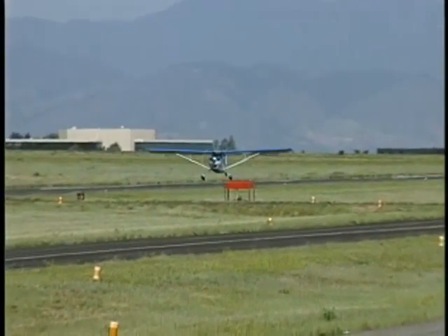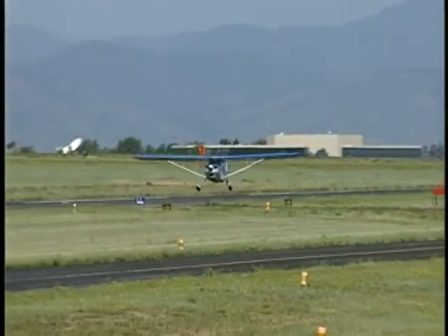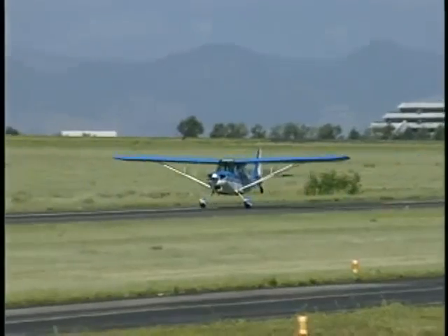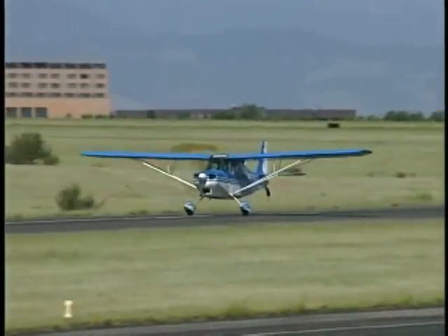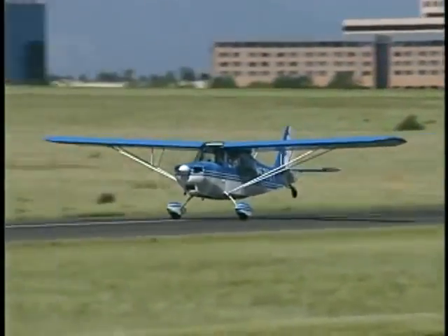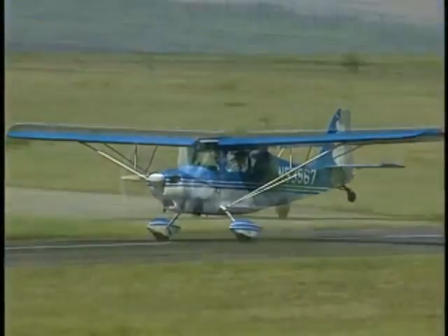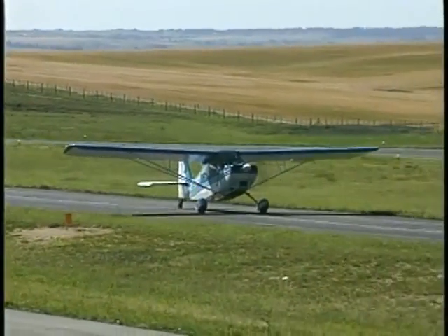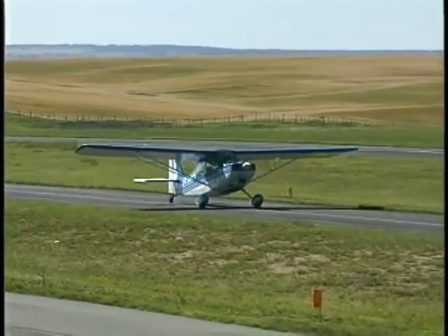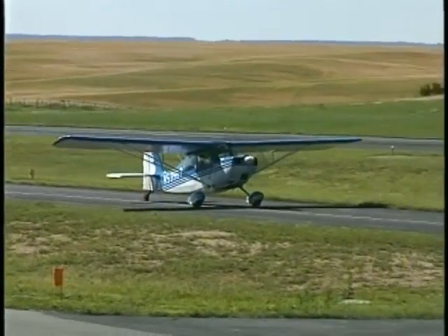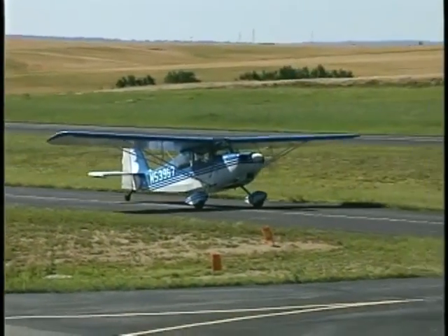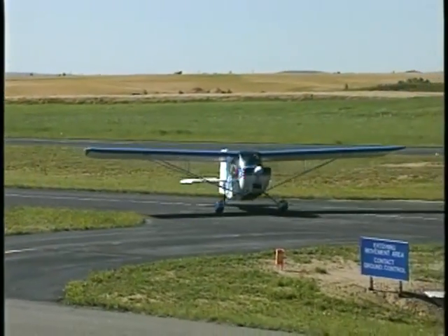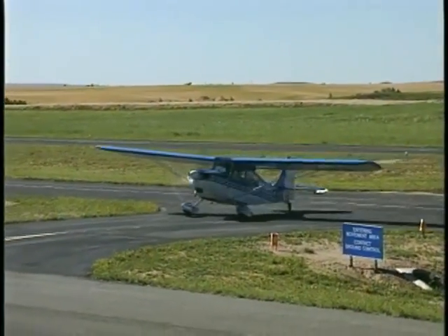Tailwheel training also introduces new procedures such as the wheel landing used in strong or gusty winds. This type of landing increases controllability by allowing the airplane to touch down at a higher airspeed and a lower angle of attack. In addition to becoming familiar with a different aircraft, a tailwheel checkout requires learning new techniques and provides an opportunity to increase flying skills. Having experience in conventional gear aircraft enables you to provide this specialized service to other pilots.